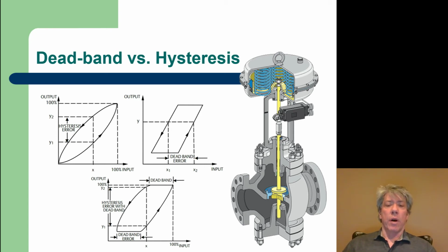So both cause problems. Now, on the other hand, sometimes with on-off control, deadband or hysteresis is necessary, particularly deadband, so that the system doesn't cycle on and off continuously. But of course our interest is in continuous controls.